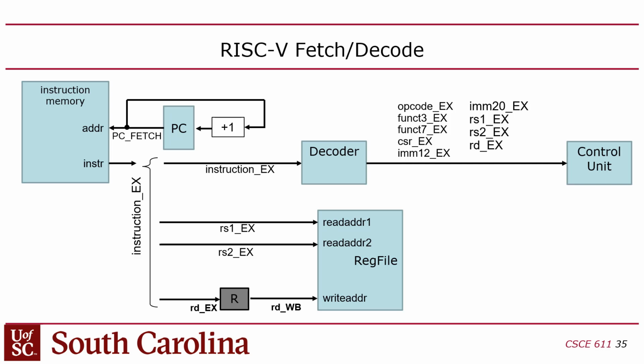As Laura mentioned, you're just going to plug the RS1 and RS2 directly into the read address 1 and 2 on the register file. There's no mux there, just a straight connection. You're just shorting them. But, and this is the part that gets confusing, the write address, that's the RD field, but not directly, because the register file is one module, but its functionality is split between 2 distinct stages.